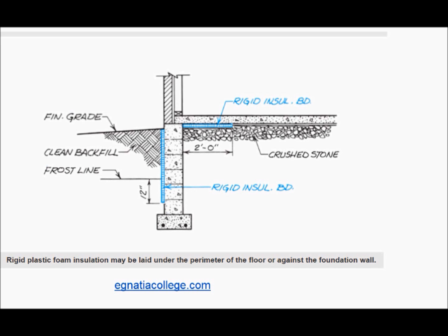slab. Like all materials, concrete and masonry expand and contract slightly with changes in temperature. To allow for this slight expansion and contraction, the joint between the concrete slab and foundation wall should include a compressible expansion joint material. Expansion joints can be made from any compressible material such as neoprene or composition sheathing material. This expansion joint filler is as wide as the slab is thick and is simply placed against the foundation wall before the concrete is placed.